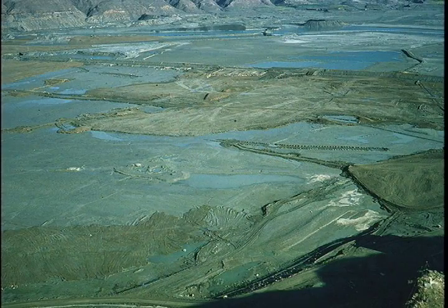Upstream of the blanket, the reservoir is in direct contact with the alluvium. This area is vastly greater than the total area of all the sinkholes. Thus, the contribution of the sinkholes to the quantity of underseepage is negligible compared to the quantity of seepage coming from upstream of the blanket. Nevertheless, it appeared prudent to monitor the development of sinkholes and to treat any that developed with barge dumping.